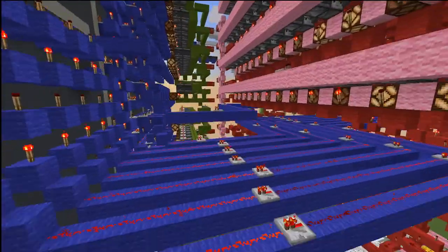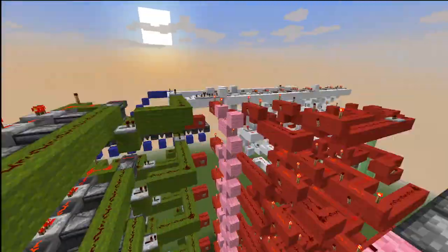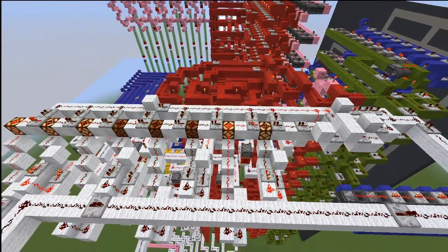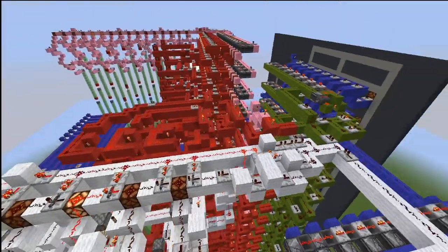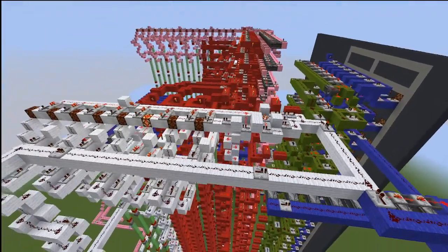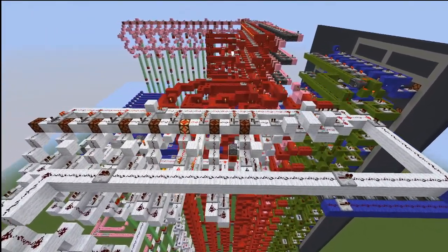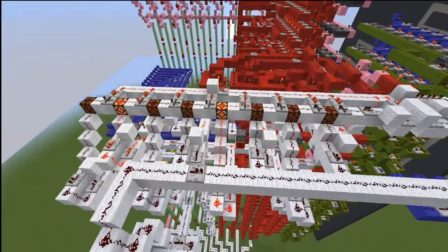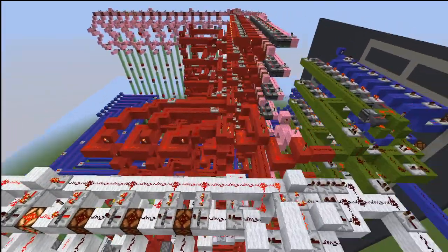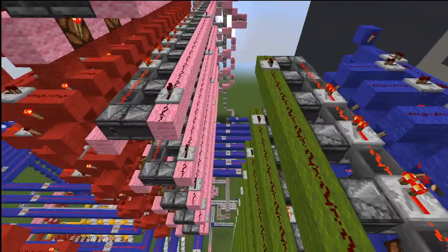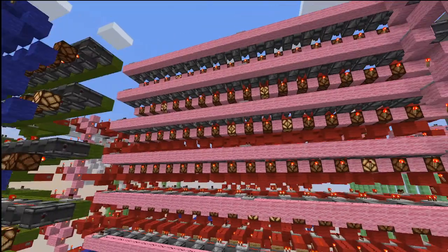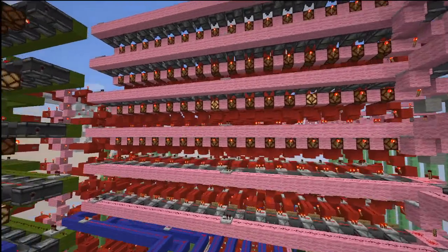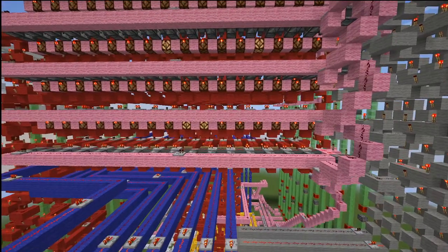And there it updated. So if I come over here, it's going to send a 4 from the program counter, because that's what the program counter is currently set to. There it is. And then it's going to select from prom line 4, which is going to give our command for jump, and it's going to say jump to line 8. So if we come down now, it's going to update the instructions. We might be able to see this in time. Oops, sorry. And there it's updated the instructions for the jump.